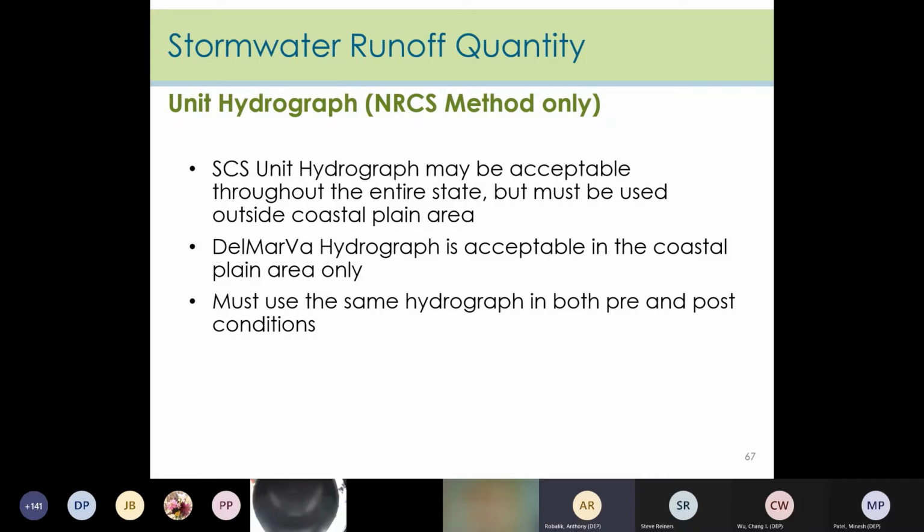And correspondingly, the Delmarva hydrograph should always be used for sites within the coastal plain area, and use of the Delmarva hydrograph is actually only acceptable within the coastal plain. So that's the clarification. But no matter where you are in the state and which hydrograph is being used, the reviewer must make sure that the same hydrograph is used for both the pre and post conditions.